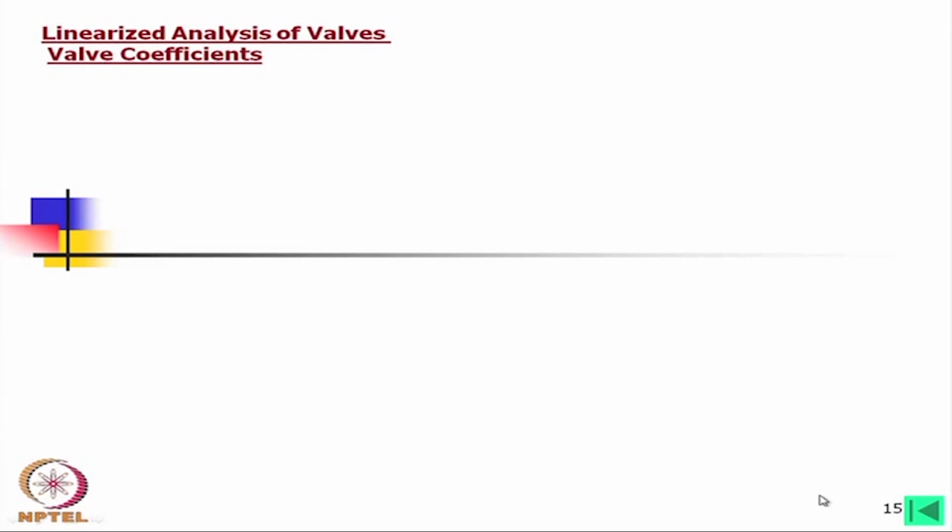Now, we will find some. So, we have only developed what might be the relation of the flow and pressure in a valve which can be used for linear control, not just on-off control. The same spool you will find is a 4 port 3 way valve. The same spool can be used, but in that case we need not accurately maintain such port configurations. In that case, we just make either full flow or zero flow.